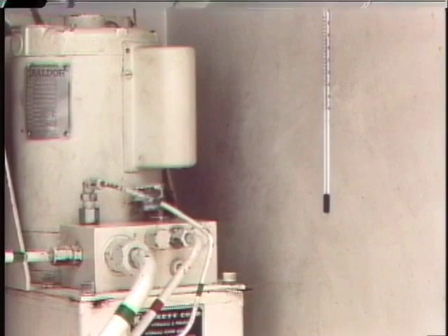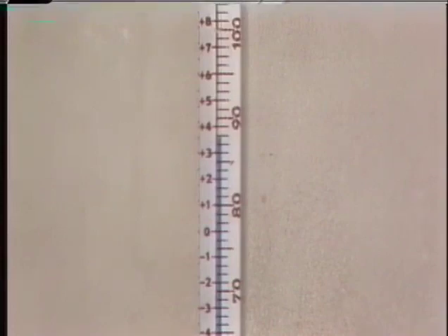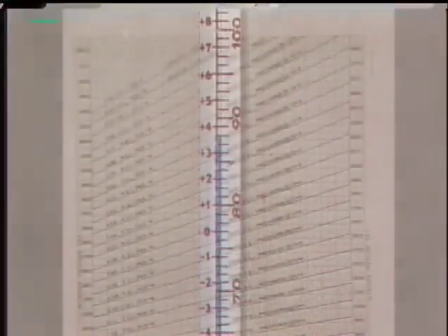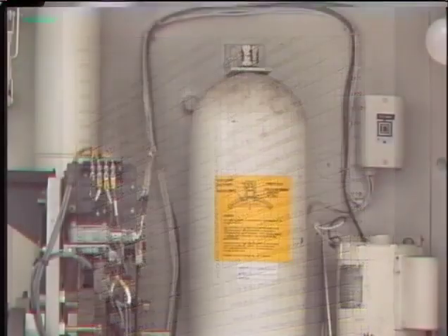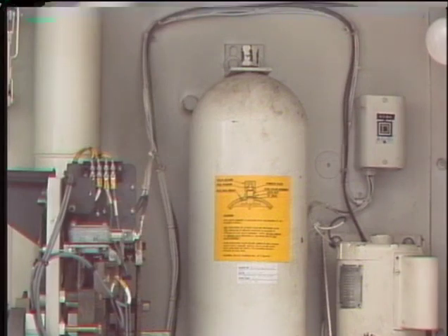Acceptable precharge pressure is usually a pressure value at a given temperature. If ambient temperature is different from the given temperature, the pressure must be adjusted to compensate for the temperature difference. The manufacturer usually provides a pressure-temperature compensation chart. Using the chart, you can determine the adjusted precharge pressure. If the adjusted precharge pressure is less than that recommended by the manufacturer or allowed by company policy, gas may need to be added to the accumulator.